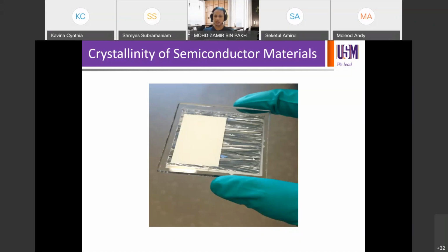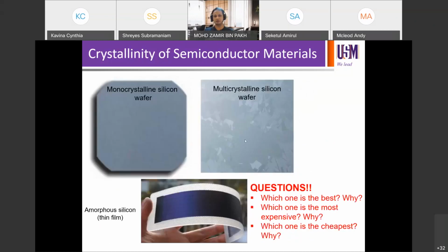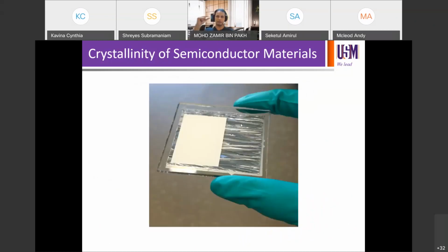or polycrystalline. So was my PhD last time. So what did I do? It was like 2016, 4 to 5 years ago, right? So what I did was I evaporated amorphous silicon using an electron beam system on a glass substrate. The glass substrate is like 3.3 mm thickness, and I use an infrared laser to scan. I just scan the laser like the scanner that you have in a 3-in-1 photocopy printer scanner. Just scan the laser on the amorphous silicon, across the film, and you melt the silicon.